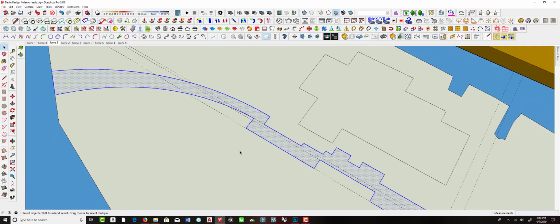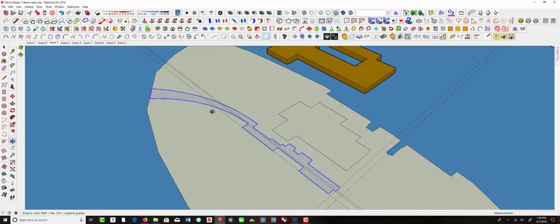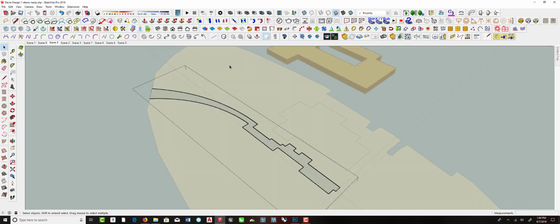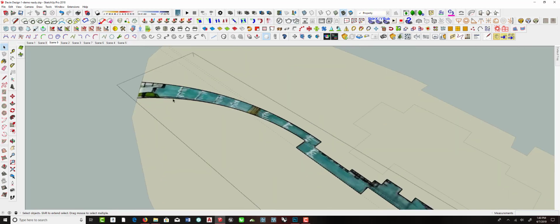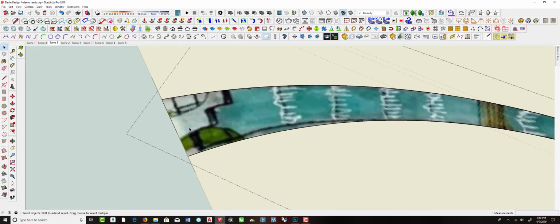So when I get done, now I can double click that. If I switch back to get off my materials, I can see that I've got that entire structure outlined. Okay, so that's one of my examples of a structure. I haven't put the lines across here yet, but I'm going to double click on that, right click, and make it a group. Okay, so now I can come in there, turn my texture back on, and I can kind of start refining this a little bit.